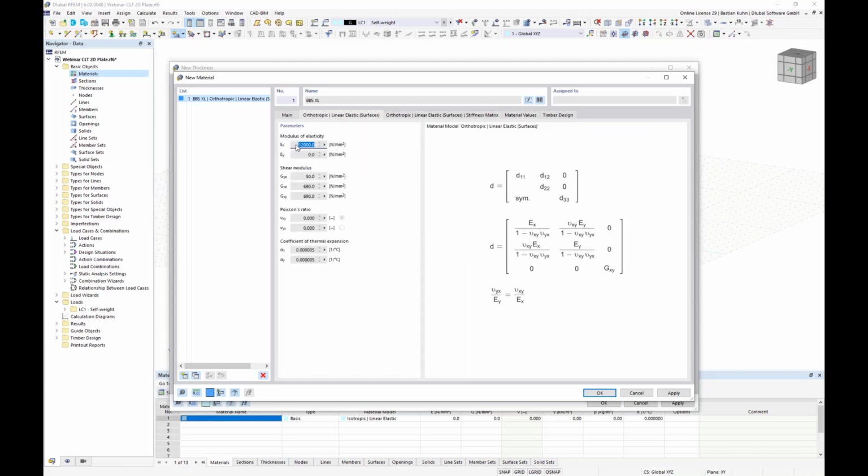It also gave a stiffness of 12,000 Newton per square millimeter in the X direction, and in the Y direction it is 0. I said it already, we cannot give you today a theoretical introduction into our design. Therefore, during the modeling process, I will show you our homepage where you can take a look into the manual, and we also offer special trainings for that. But now, just to say, in X direction it's 12,000 Newton per square millimeter, and in Y direction, for one layer, we have a value of 0.